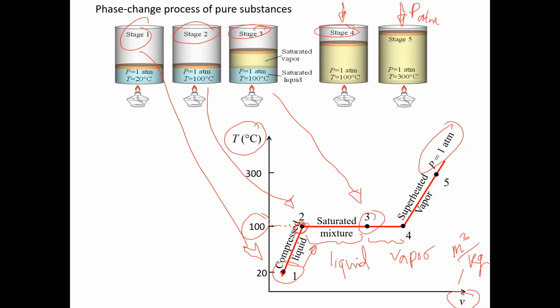But the temperature is the same because we still didn't change the liquid completely to vapor. Because of this, the temperature will be constant. So we keep adding the heat until we reach number 4. Point 4 represents the end of vaporization.